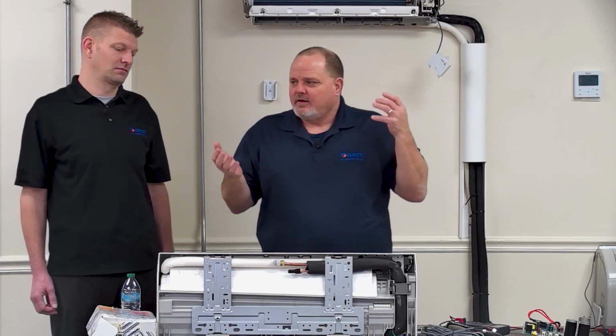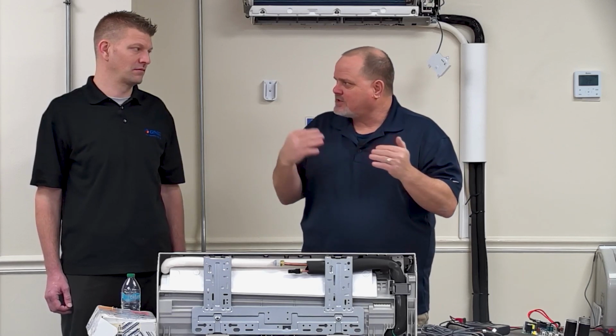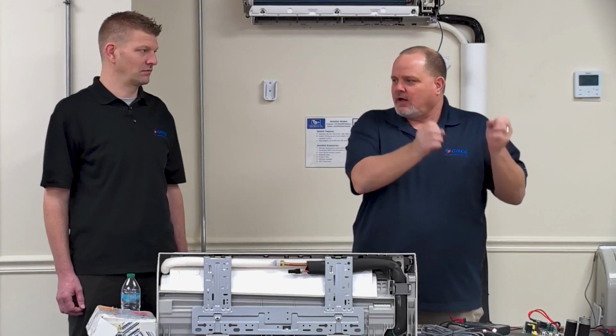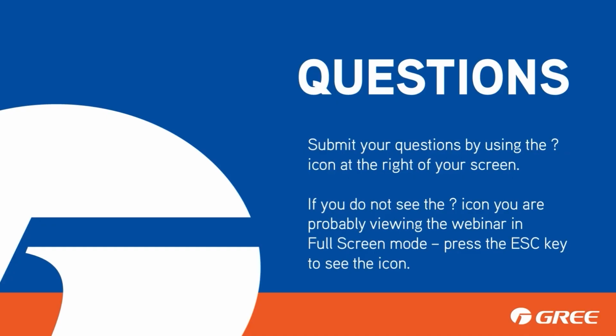I can't talk specific to every job, but what I'm saying is use your mind a little bit and think about where the best place is to flow my nitrogen from to make it convenient for me to make my joint, know I have nitrogen in that pipe, and then move on down the line and work your way back towards that condenser. That's what I'm trying to get at here.